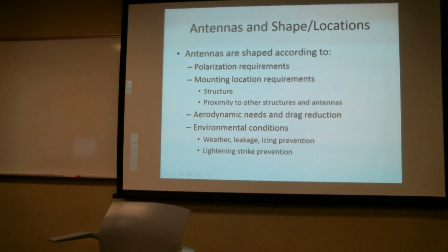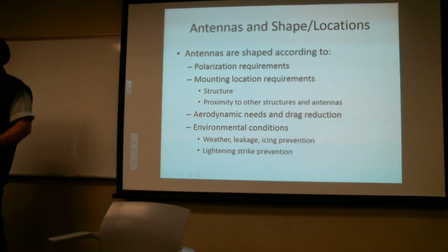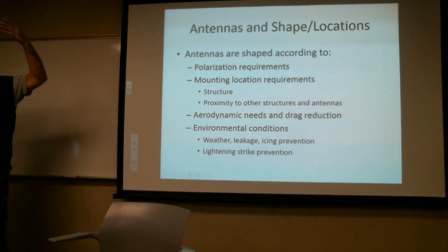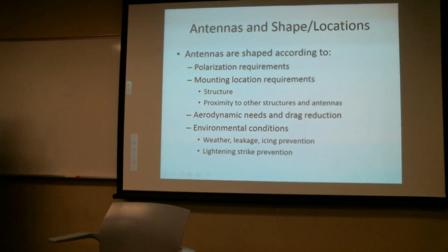So mounting the antenna on the fuselage, it will interfere with forward projection if that's important to you. Now, a lot of times what we'll do is we'll mount it on the fuselage, but up on a vertical stabilizer, so it's up high, so that 72-inch thing is sort of shifted off a little bit, and it can get around it fairly easily.